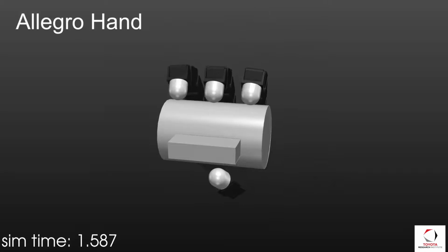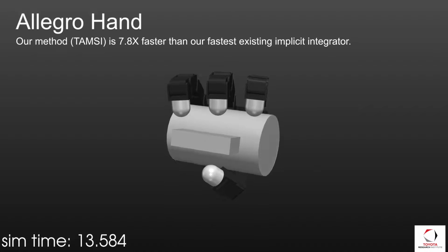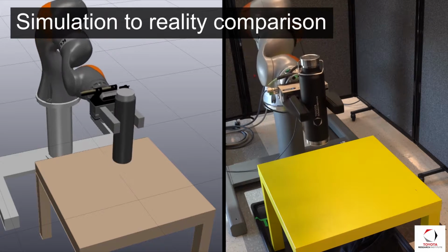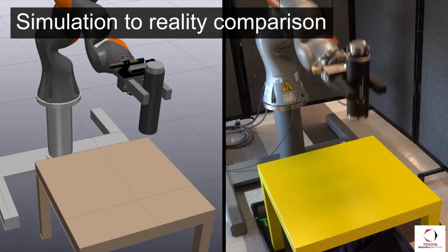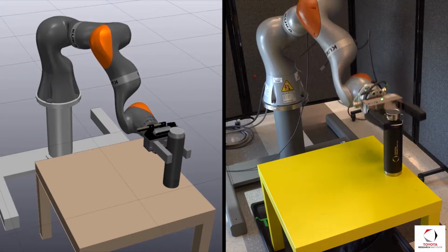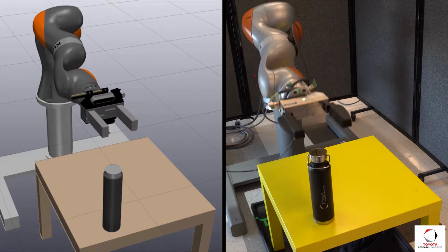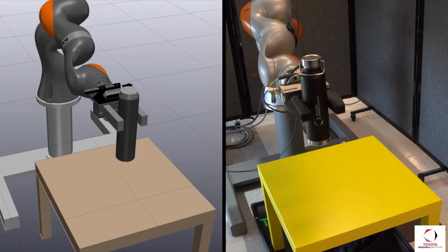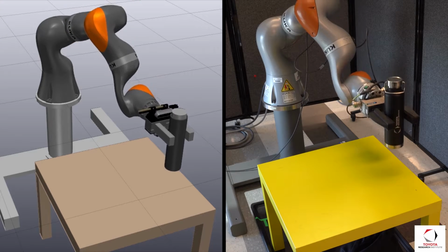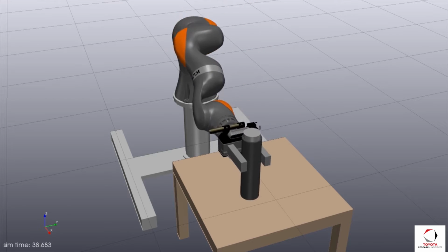We evaluated the performance of our TAMSI method on a complex manipulation task using a 16-DOF Allegro hand with multiple points of contact. We demonstrate the robustness of our TAMSI method to simulate a manipulation task with vigorous shaking motions emulating disturbances. A Kuka-Iwa arm is commanded to pick up a bottle, execute a shaking motion, and set it down at a specified position, where force feedback is used to assess grasp quality as well as task completion. We show that our framework is ideally suited for prototyping controller processes for manipulation that seamlessly transfer to reality.